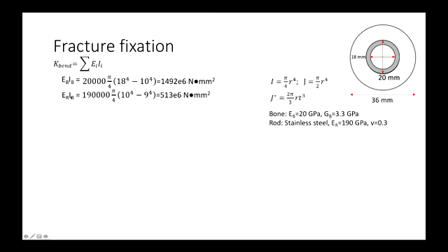And then for the rod, same thing again. It's a tube, so you have the outer diameter subtract the inner diameter, and we get this value. Add them together, and that's the bending stiffness. Is that clear? So what about the split?